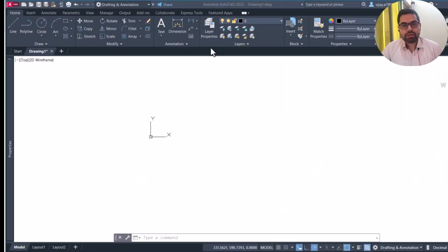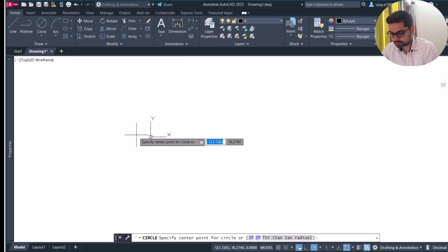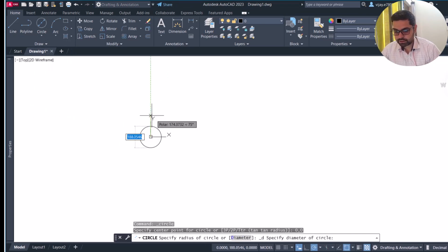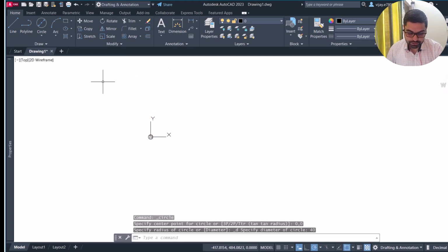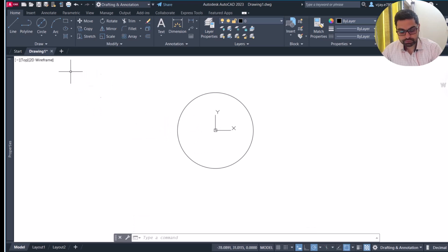So we will start this drawing from the upper circle of diameter 40 units. So let's start. We are going to select circle using center and diameter, then specify center as origin, specify diameter as 40 units and then press enter. After that, we are going to zoom in using the roller button of the mouse to the required level.